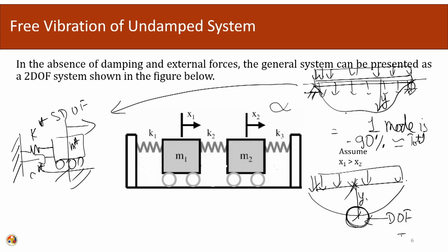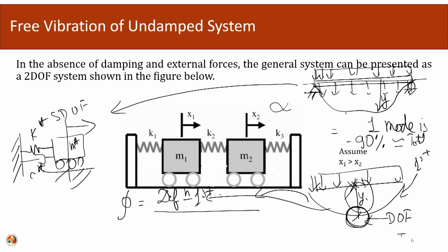So, the shape is the first mode, and the chosen degree of freedom is the vertical displacement at the center. Using this theory we constructed our shape function. The shape function is the deflection equation mimicking this particular mode, and the denominator is the deflection equation evaluated at the required degree of freedom, y, at x equals L over 2.